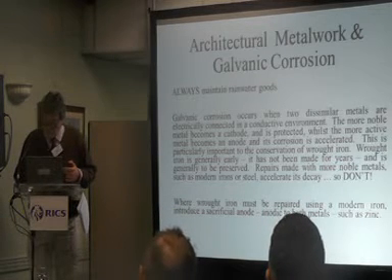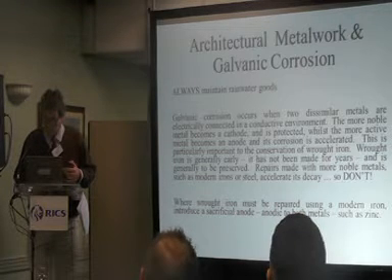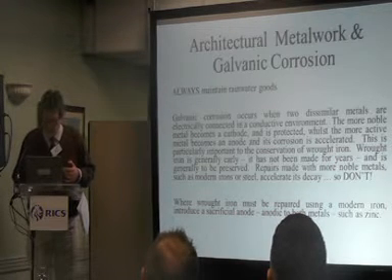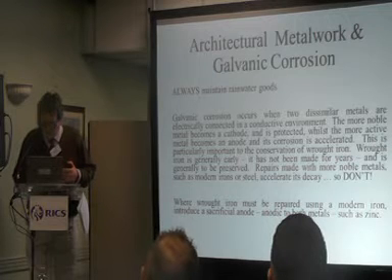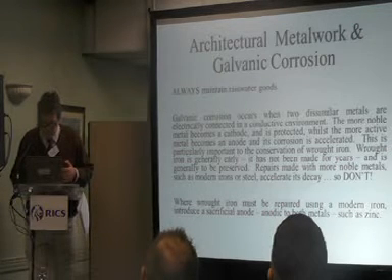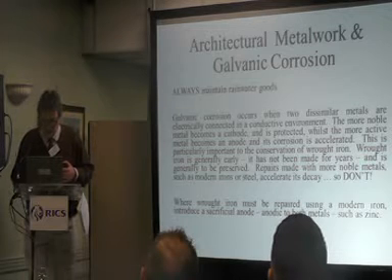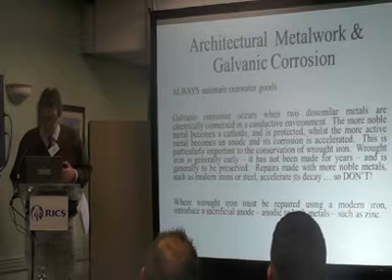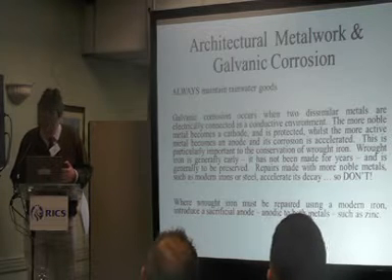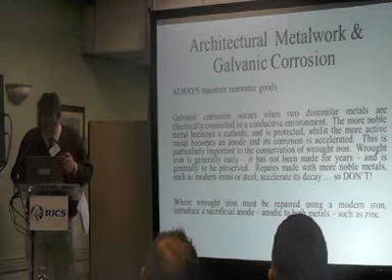it matters very much. Wrought iron is special. It's rare. It's wonderful when you come across it. It's generally early because nobody's made wrought iron for a couple of centuries, I think. It's generally to be preserved. Repairs made with more noble metals such as modern iron and steel accelerate its decay, rot it. So don't do it, ever.